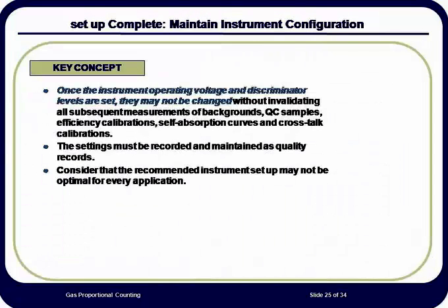The overall checklist for instrument preparedness is: gas quality is appropriate, gas flow rate has been set and is constant, operating voltages for plateaus have been established, self-attenuation curves have been determined, crosstalk factors have been measured, quality control checks have been performed. Once all these tasks are completed and the information recorded in the appropriate quality assurance file, the system is now ready to be used for counting. None of these parameters should be changed. If they are, setup and calibration may need to be repeated and voltages and settings reestablished.